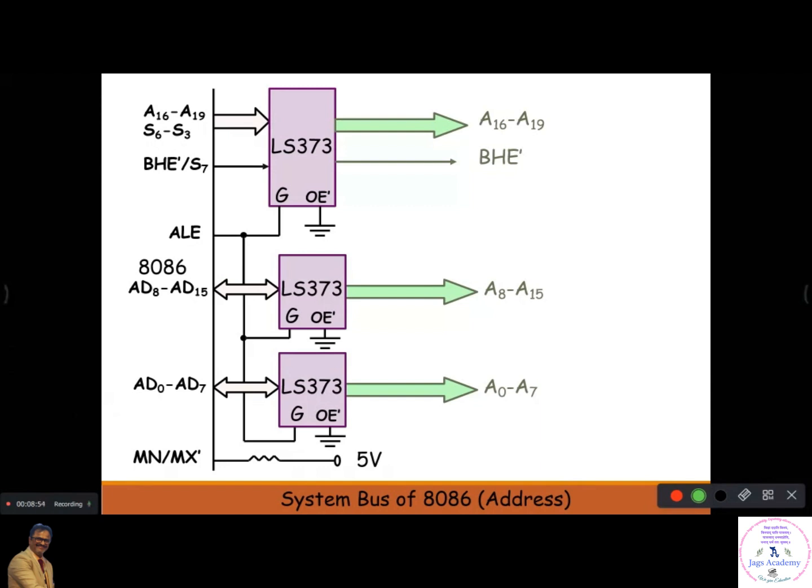This is very important. In this picture you are going to separate only the address bus. This is your microprocessor side. Now you see here the LS373; the 273 is all going to be the same thing, so don't worry about it.